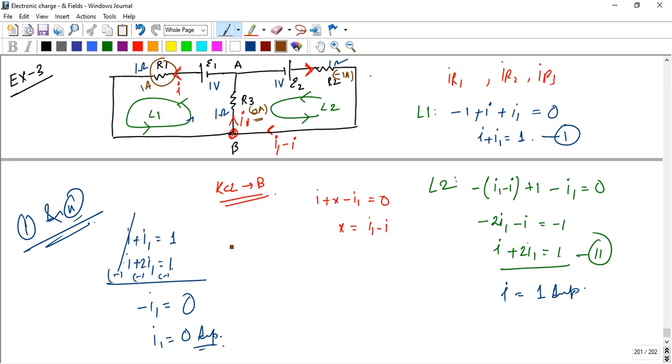This means there is minus 1 ampere in that direction, and here it is plus 1, so these two cancel. That's why we leave these two points; the currents 1 minus 1 plus 1 minus 1 give 0. This is the very basic way: first apply KCL and get all current directions, then finally apply KVL to solve.